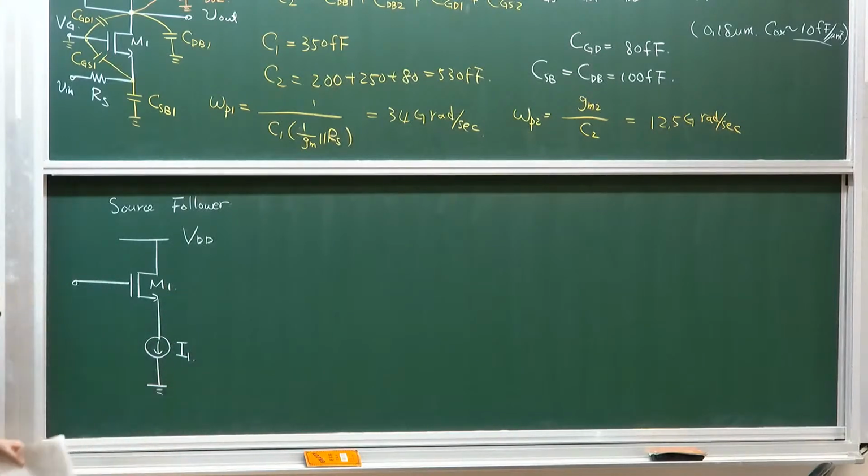Okay? And because of this type of circuit, we're going to add the external capacitance in this discussion. The main purpose of a source follower is to either drive a low resistance or a high capacitance. The main purpose of a follower circuit is to provide current to drive a node. And this is very commonly seen, especially in internal circuit design.